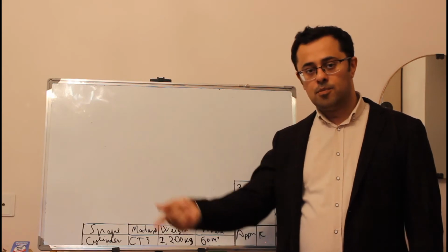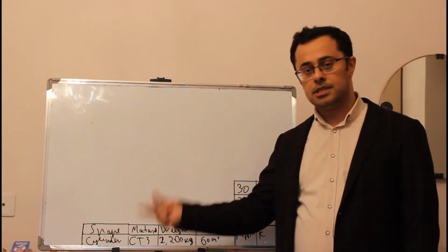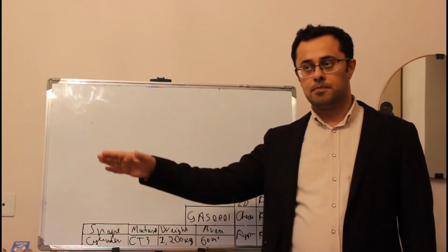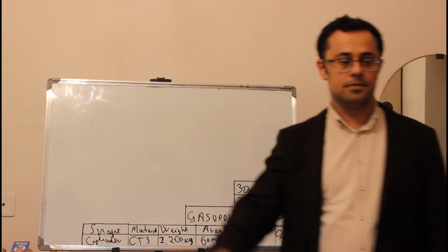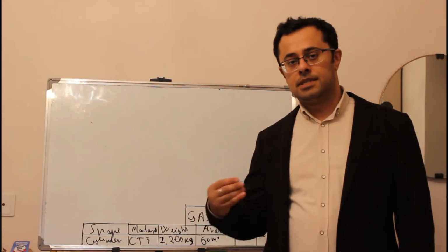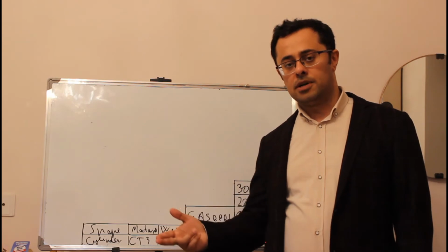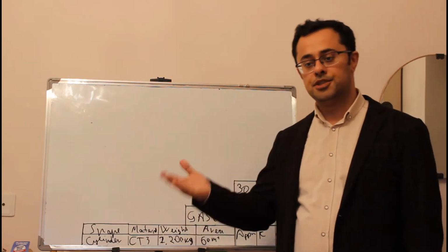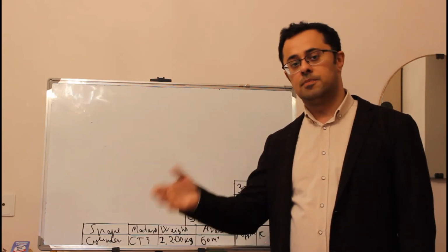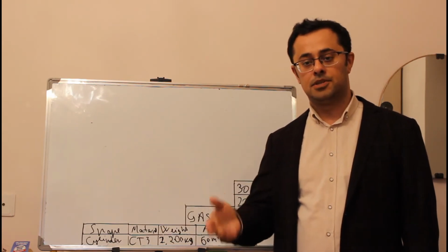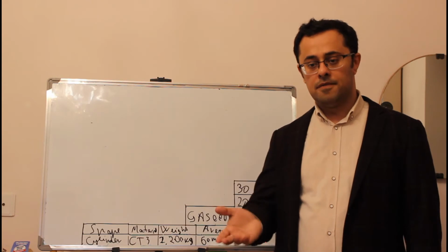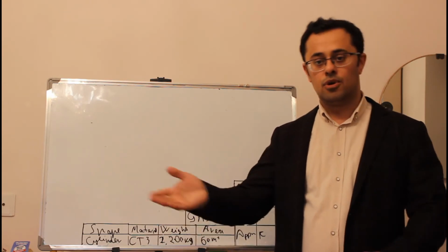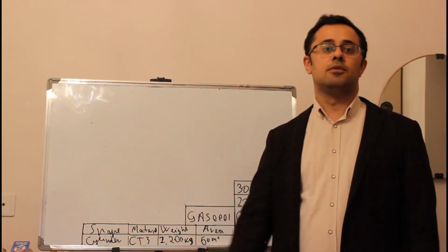The point is that if it's cylinder, they send it to the department which works with cylinders, which cuts cylinders. If it's sheet metal, they send it to the department which has plasma machines to cut the metal. If it's round bar, they send it to turning machines to make the operation.